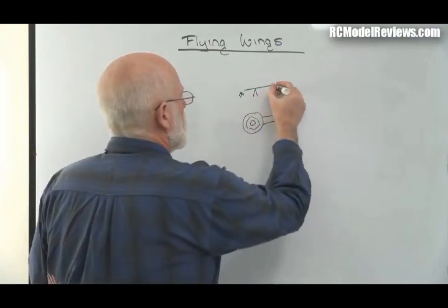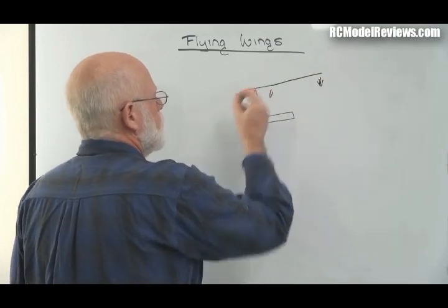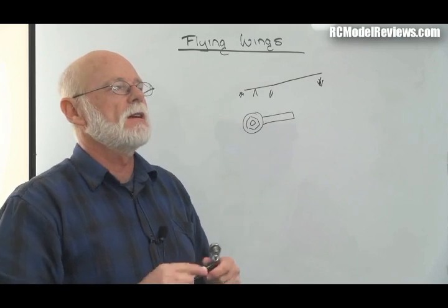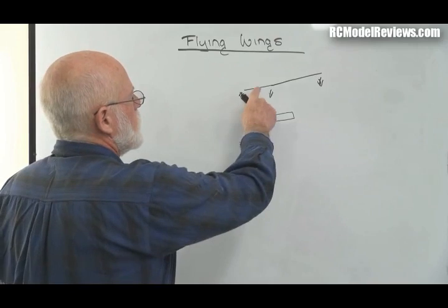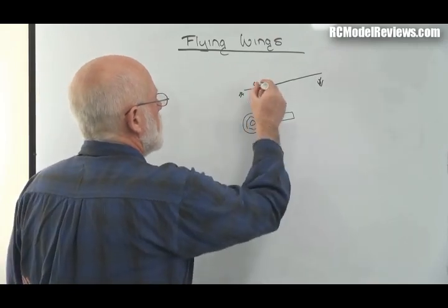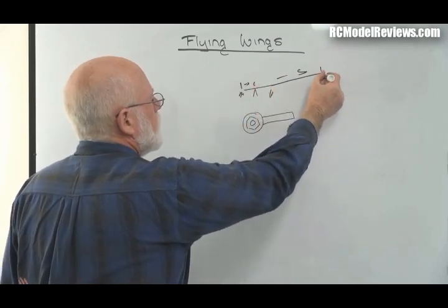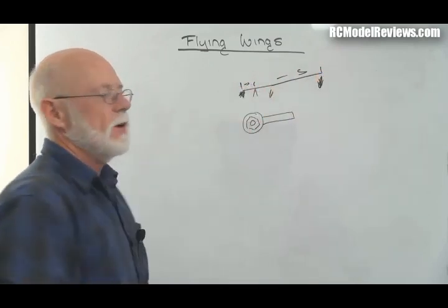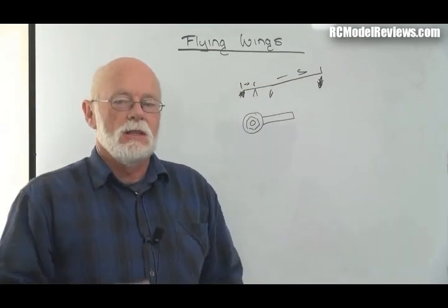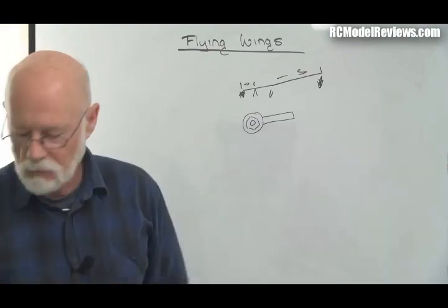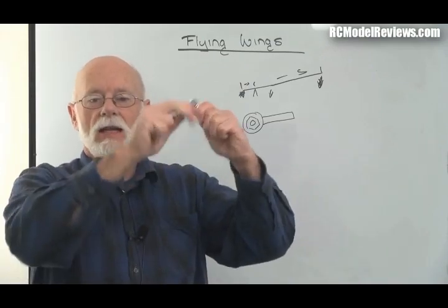But if you make a long lever, like that, then when you move this down here, the force here can be much greater. I think somebody said, give me a long enough lever and I'll move the earth. And that's true, because if this distance here was 10 times longer than that distance there, then for every unit of force you apply here, you'll get 10 units over here. So you magnify the force. It enables you to apply a lot of force with a little bit of force. It's a force amplifier.